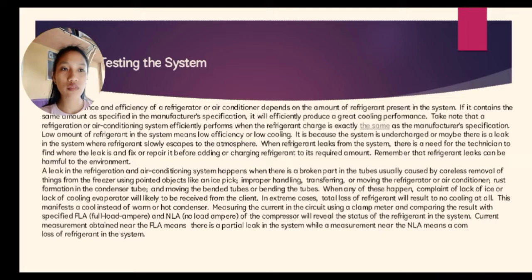When any of this happens, complaints of lack of ice or lack of cooling in the evaporator will likely be received from the client. In extreme cases, total loss of refrigerant will result in no cooling at all. This manifests as a cool instead of a warm, hot condenser.